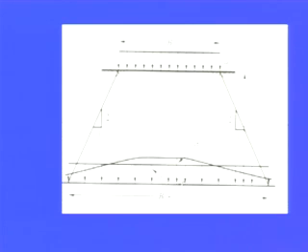Now, there is an approximate method, known as the 2 vertical to 1 horizontal distribution of pressure, which we discussed in the last lecture. Here, there is a loaded area of width B and load intensity q applied to the soil.